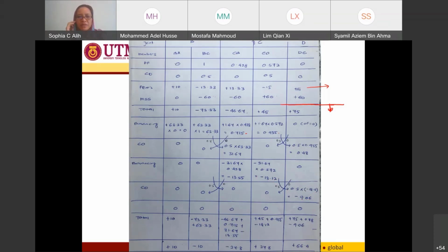If I distribute it for this, since this distribution factor is 0, in the end I will have 0 in here. So all the lines here, I have already 0, 0, 0, then I can stop. So in order for me to calculate the end moment at the end of my calculation, I need to just take from here down and sum up everything.